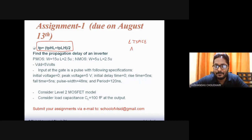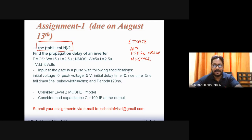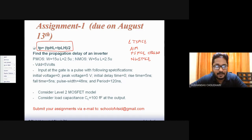Then you have a few more SPICE based software, that is AIM-SPICE, and PSpice by OrCAD, which is used in the Cadence tool. Student version copies of these you can obtain. And then there is one more open source, full-fledged freeware called NG-SPICE. Any of these you can use to simulate your designs, to find out the propagation delay of this inverter with these specifications.